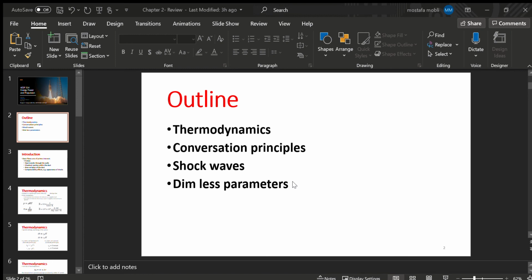Okay, there is a very small mistake here. This should be negative dP. Okay, take a note, this should be negative dP. But you can use the conservation of mass equation for this case, plug it in here, and get to this equation: u squared d rho is equal to dP. And the main assumption we had was that this is an isentropic process, so entropy is constant. u squared is equal to dP over d rho, or partial P over partial rho, where entropy is constant.